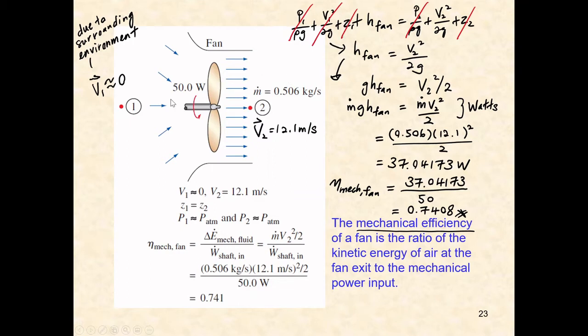That's why we have the energy at point 1 plus the energy given by the fan. So the existing energy at point 1 plus the energy given by the fan will be equal to the energy at point 2. So whatever kinetic energy is given at point 2 should be coming from the fan, because if no additional energy is provided to the system, point 1 and point 2 should have the same mechanical energy.